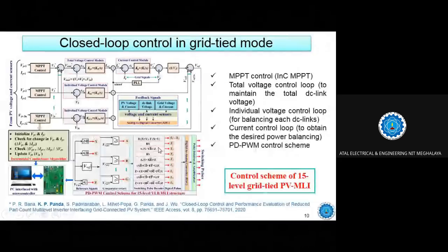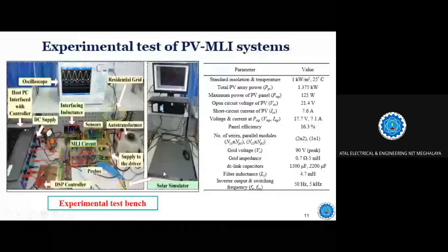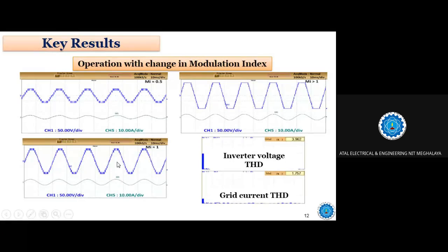See, this PWM logic is not going to change at all. This PWM logic is set in the inverter. Because of the change in the reference signal, the reference voltage, the modulation index is getting changed. If the modulation index is changing, accordingly some of the switches are not getting pulses. The pulse is going to change because of the change in reference signal, so the inverter will produce the output accordingly. Is that clear?